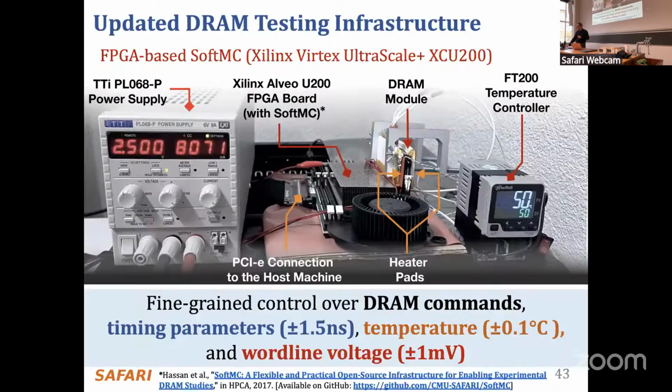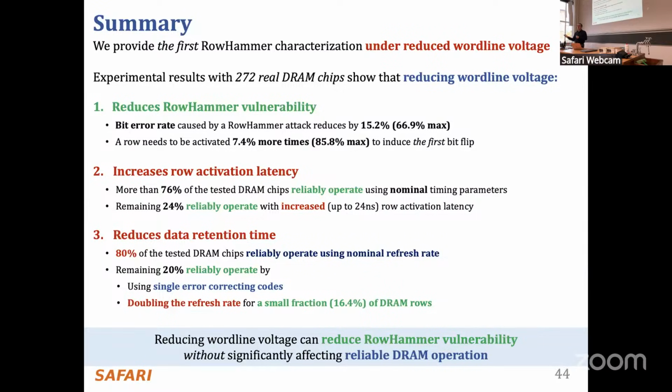So intuitively, well, again, for this, the infrastructure needs to be extended so that you can measure voltage nicely, or you can modulate voltage effectively. And basically, intuitively, what you would expect is if the voltage level that you apply to a word line is high, you should cause more disturbance, right? Because you have a lot of voltage, and that should affect cells around you more. If the voltage level is low, you should get less disturbance. And that's what we observe, actually. So basically, that's the good part, essentially.